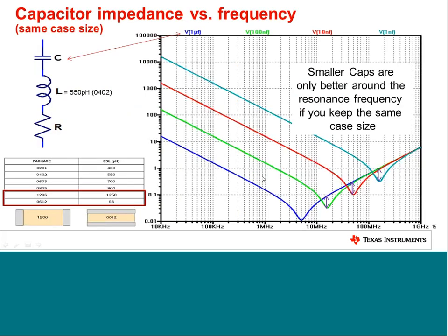If you look at a capacitor, you can use, or you will use with such a circuit, you never get a real capacitor. So you want this, and you get this when you buy a capacitor. It has a mechanical shape or dimension, and this means it has inductance, and the material which connects the capacitor has resistance as well.